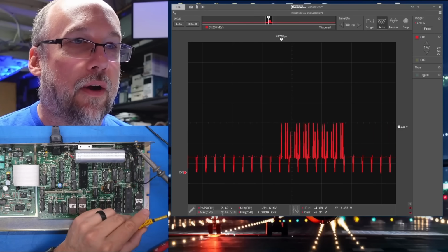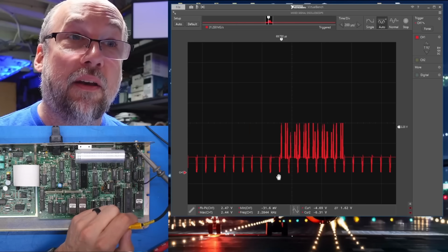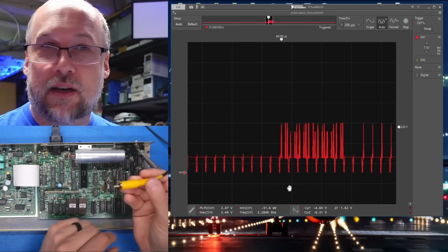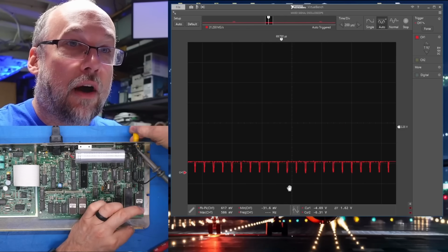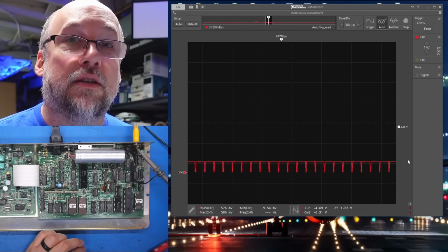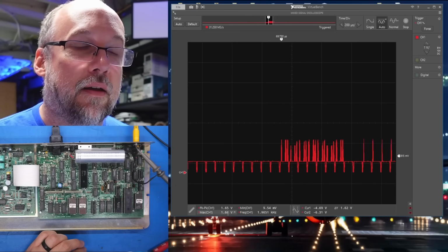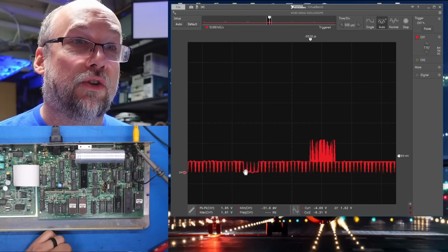By the way, looking at the video output on the scope, we're seeing that the peak to peak is 2.4 volts, which is a bit higher than I would expect. Usually you get 1 volt peak to peak, but without a video cable plugged in, the output is not terminated. So when I connect this to the retro tank, it should drop the video signal. And it did. And we just have to adjust the triggering here just so we get to trigger off that again. And 1.6, it's still quite the hot video signal, but it looks good.